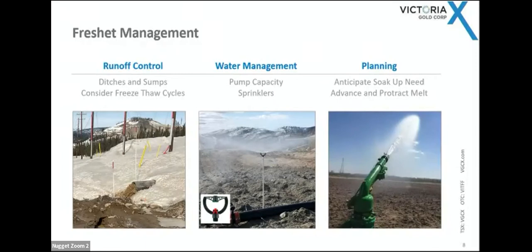The next thing that I really didn't have an appreciation for until I lived it is that the freeze-thaw cycle is real. Something that might be okay today is going to get wet, it's going to freeze, and then the solution is going to go in different directions. You've got to be prepared for it. It's now standard practice for everything we do. Beyond that, we have all this water to deal with. It really comes down to pump capacity: have the pumps where they need to be, and move that water.